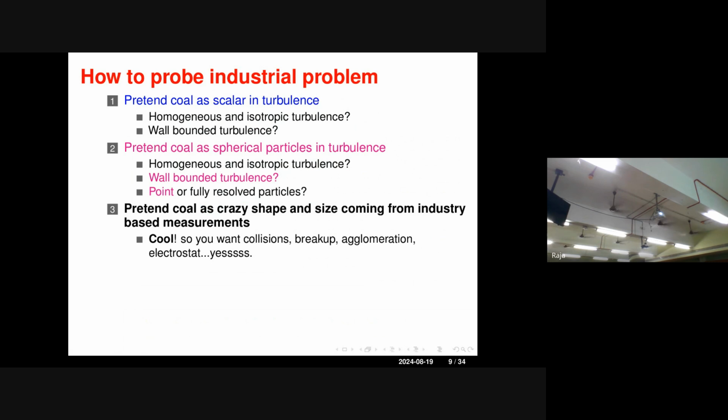Even what it means to be a particle: any industrial problem always has crazy shapes. This spherical kind of thing is very abstract. They will be very sharp, and they will start interacting with each other. More complex shapes you will have. They are not spheres, they might be cylinders, tapered, just take sand grains and try to sense them. Now, if I want to simulate that, how am I going to do it? Discrete simulations are the only way.